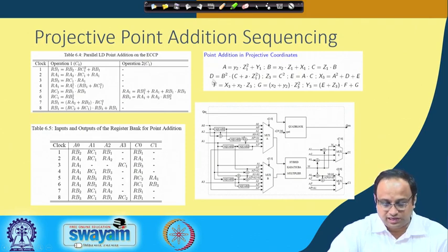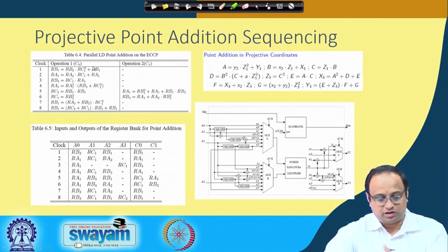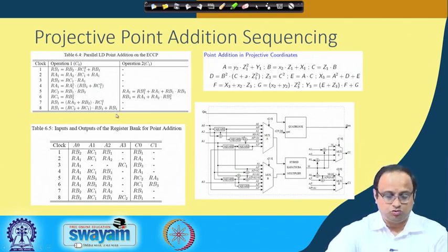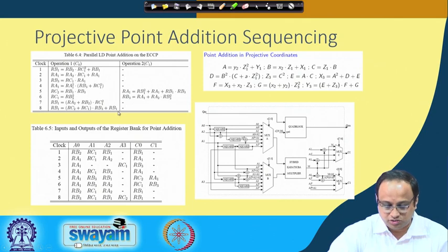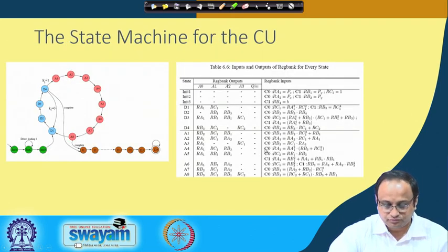Here you can verify that I have got 2 outputs which I can produce in parallel. Every clock cycle I am using 1 multiplication; the multiplier is always used in every clock cycle. The other component or other output is often used to do peripheral computations. So in that case you have got 8 time steps which are required.